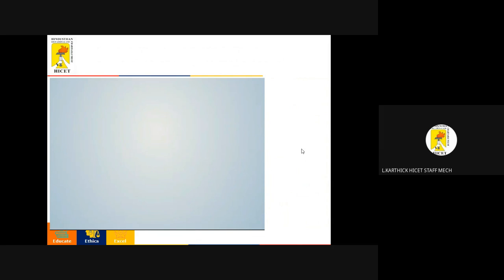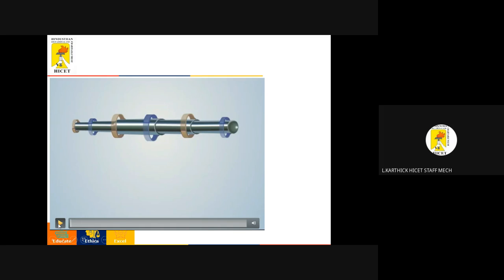So these are the differences between the solid circular shaft and the hollow circular shaft. The major things we have discussed are the expression for torsion, the difference between the solid shaft and hollow shaft, and the polar moment of inertia, how it twists and how we are going to calculate it. In this video we also came to discuss stepped shafts. So how are we going to calculate the torsion equation for stepped shafts?